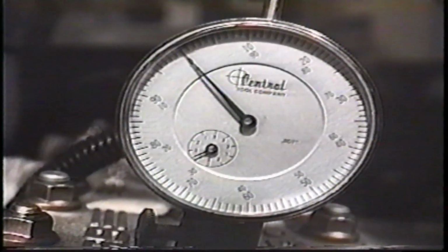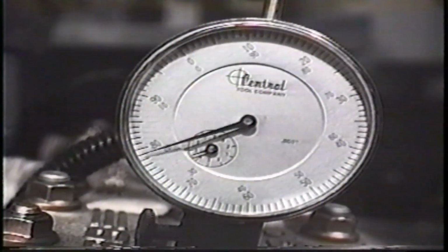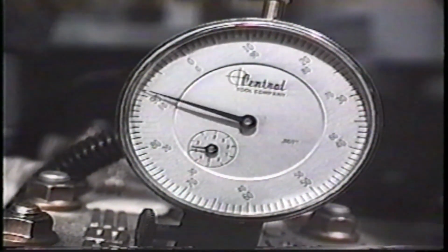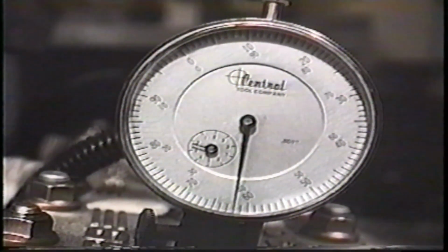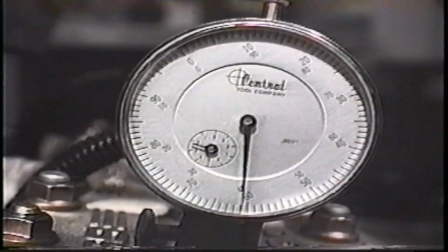Turn the crankshaft the opposite way it turns during operation until the indicator reads the specified measurement. In our case, it's 0.139 inches. This is the position of the piston and crankshaft when the spark should jump across the air gap with the engine turning at 3000 RPM.